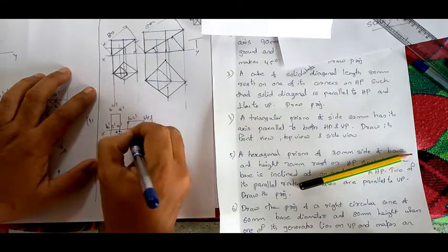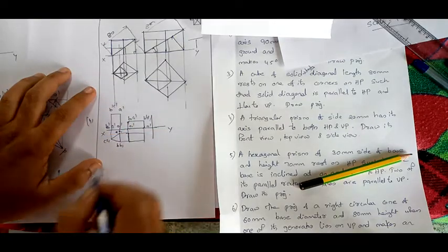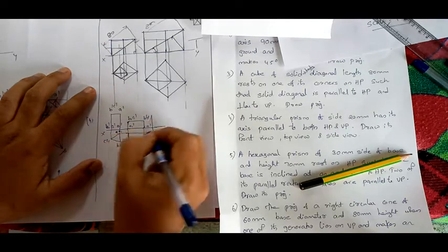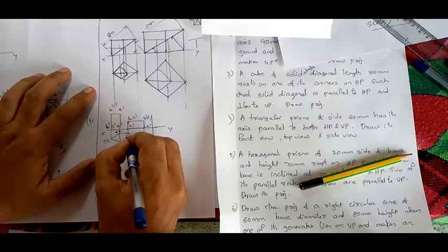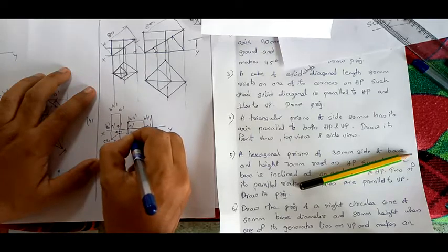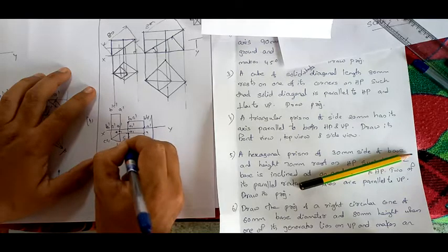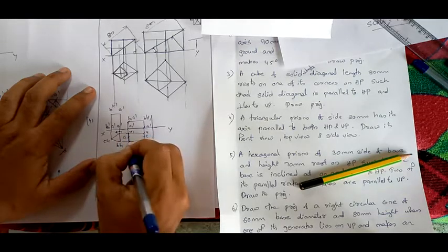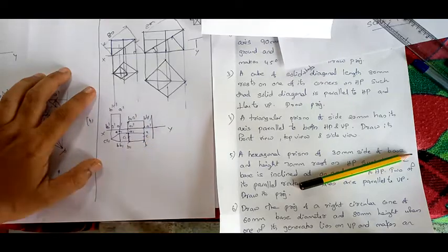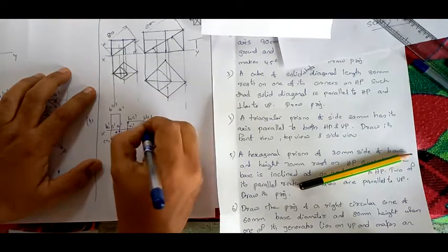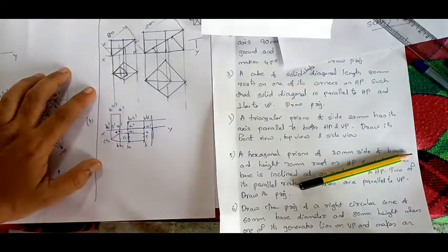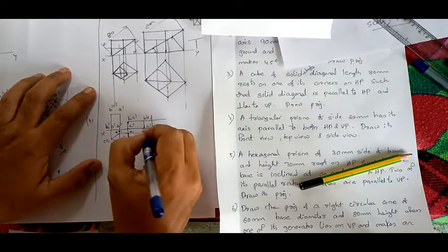Here you have A dash and here you have A1 dash, right? So here you have A and A1. A1 is here, A is here, C1 is here, C is here, B1 is here, B is here, right? So you can find the point. What you can do is project rightwards, and you will obtain the corresponding front view.